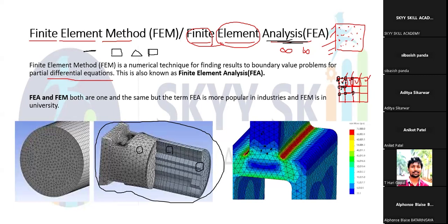Okay, it can have two element shapes. That is, one is your triangle, another one is your quad. For your 3D elements, we can have four. That is tetrahedron or tetra, then penta, then wedge. Sorry, penta or wedge, then hexa. This is my hexa.